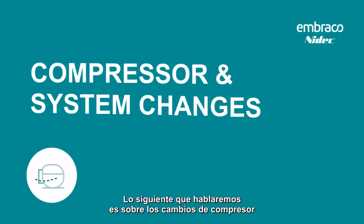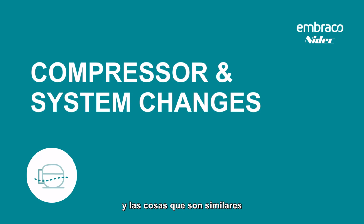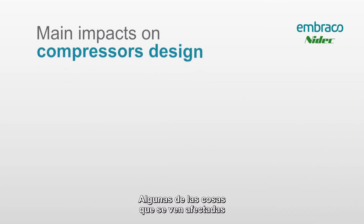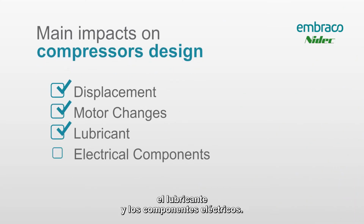The next thing we'll talk about is compressor changes, and specifically some of the things that are different and the things that are similar about the compressors used for R290 and R600A, and then also with the systems. Some of these things that are impacted include the displacement, motor changes, the lubricant, and the electrical components.